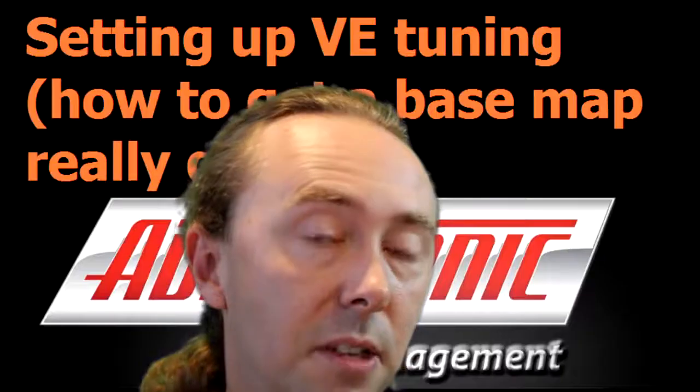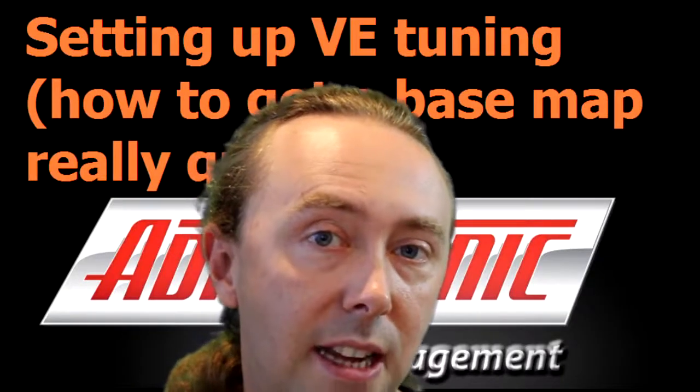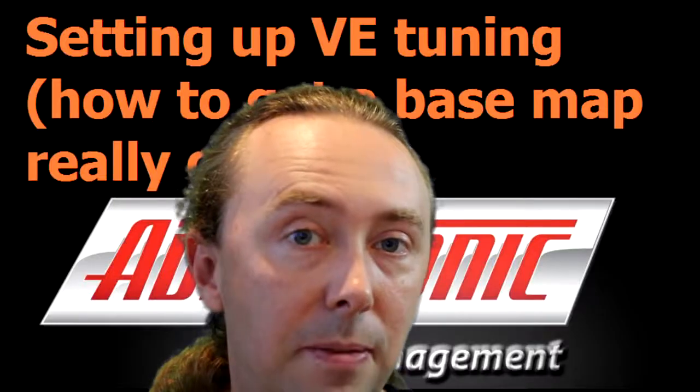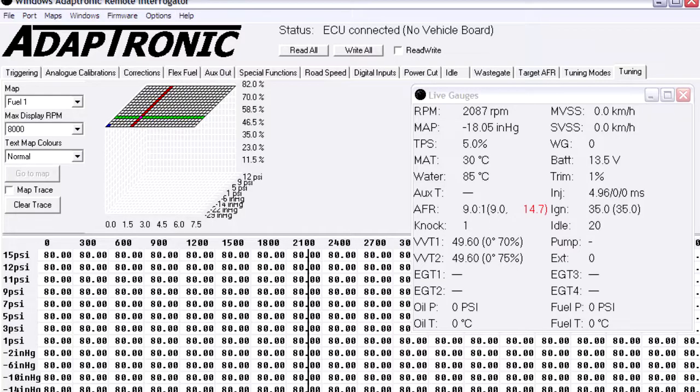The next thing that you have to do in the setup is make sure that your target air-fuel ratios or lambda values are set appropriately for the engine. From there, start with a fuel map of constant values of say 80 or 100, and this will allow most engines to run pretty much straight away. From there, it can be tuned as normal.